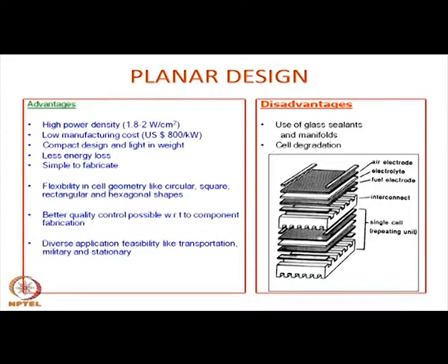Well, that is the structure of the planar configuration which we have shown earlier. So, these are the two disadvantages, one is the glass seal and the other is cell degradation. Cell degradation is also a problem, which means the overall life is a little limited. So, these are the two disadvantages so far as the planar design is concerned.